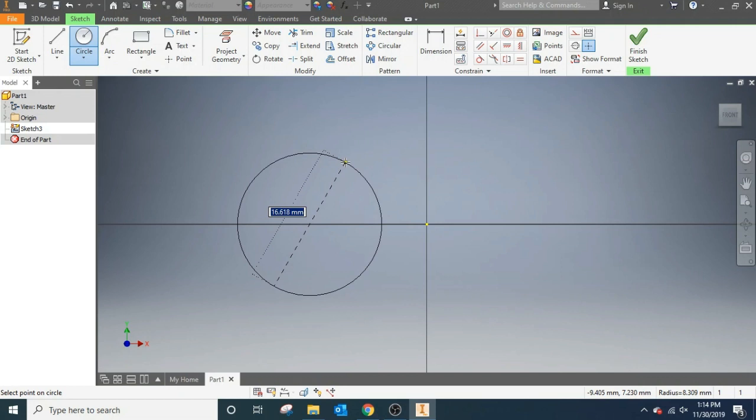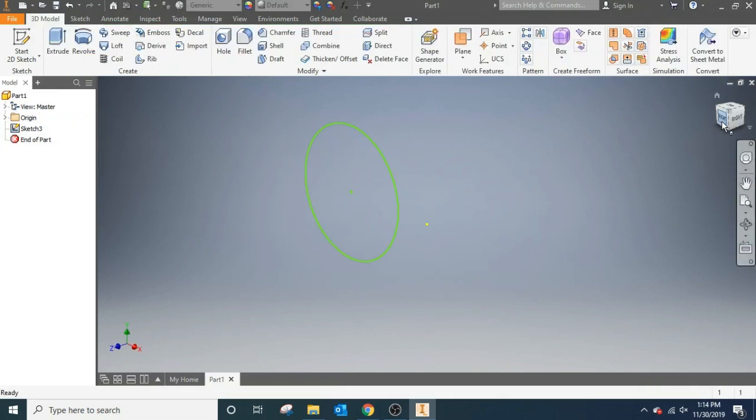So I'm going to show how you can use the Revolve tool to make a 3D part with the axis outside of the part that you're making. So I'm going to use the y-axis, and it's going to be to the right of the actual part. And this is going to make sort of a 3D toroidal donut shape. So I got my profile.